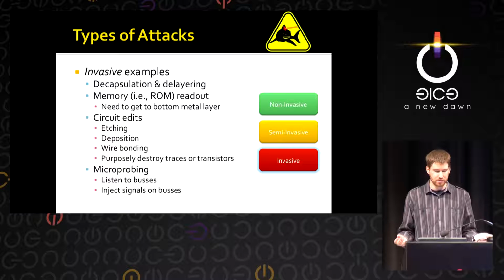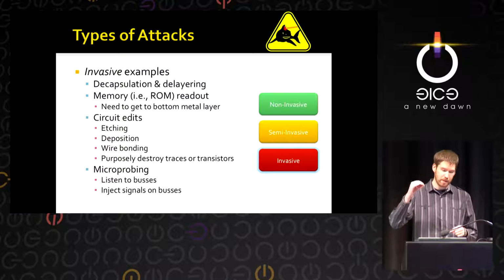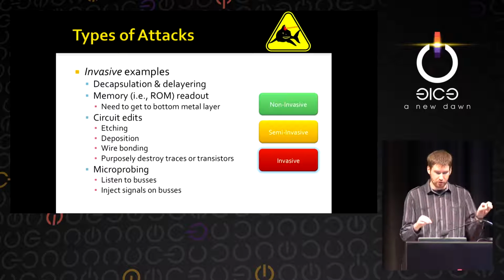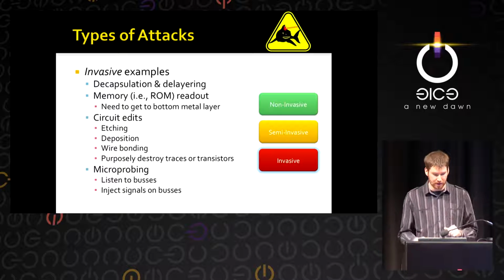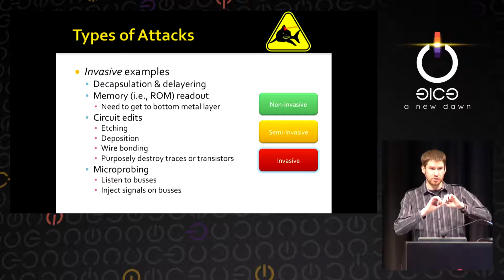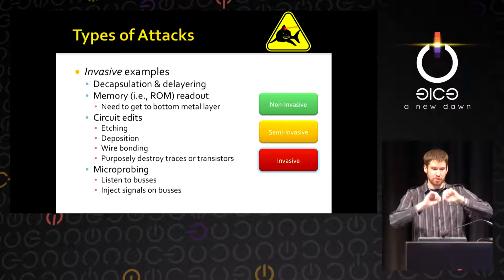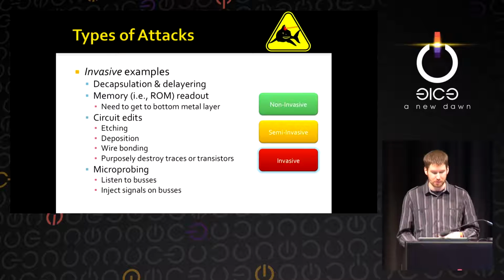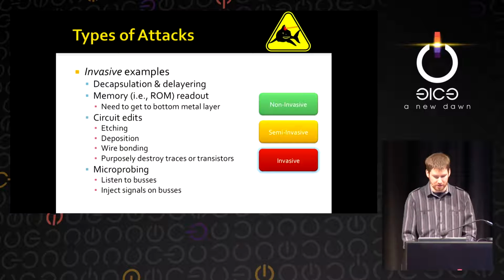Deposition, where you're using something like platinum or tungsten to deposit conductive material on the surface, so you actually create a conductive path. Wire bonding, where you're taking a wire bonding machine and putting gold bonding wires from areas of the chip out to a larger, more human-friendly package, like a very large DIP package, where it's 2 rows of 10 or 20 pins or whatever, and then you can easily work with that.